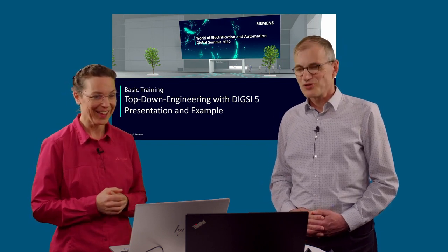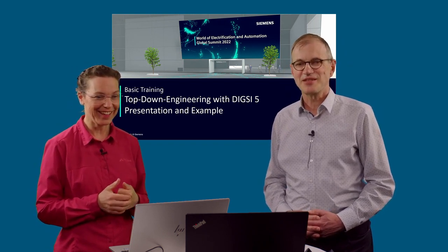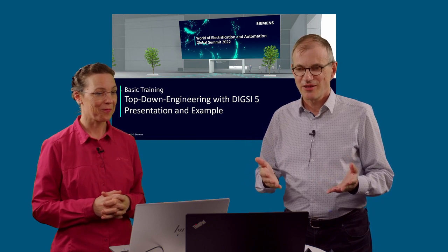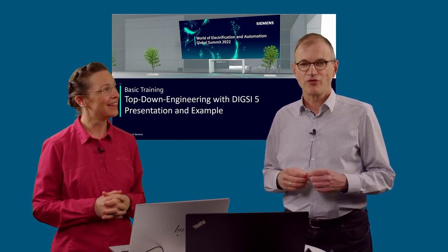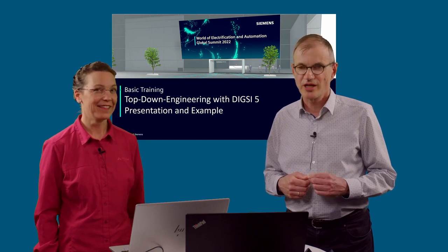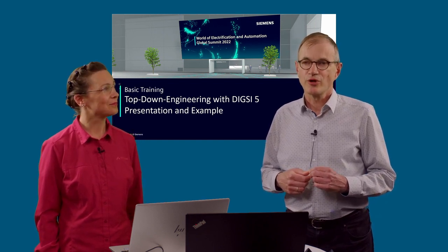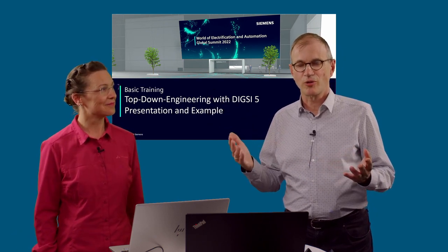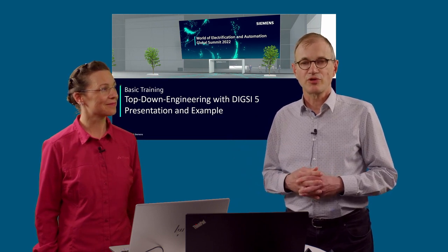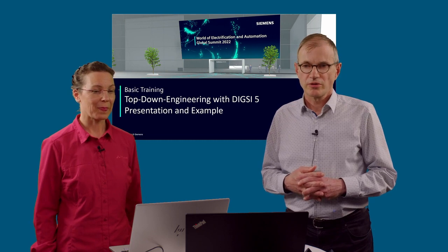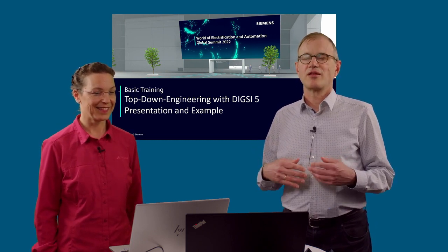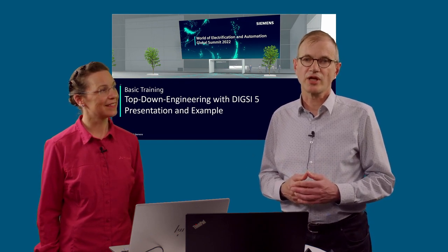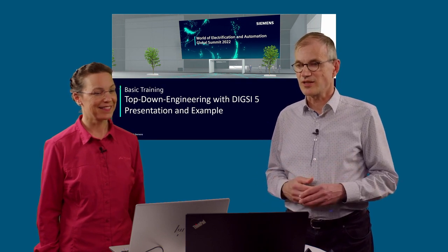I don't. Syscon is not an SCT. It misses some basic functionality. It does not have a library where you can drag and drop the functionality. Syscon is designed for configuring the communication part of a substation. It has no library where you can drag and drop PTOCs or topology or some things like this. It's a pure communication editor. So no, it can read the SCD or the SSD file. It can add communication, but it cannot create a requirements list from the functional side of the devices.